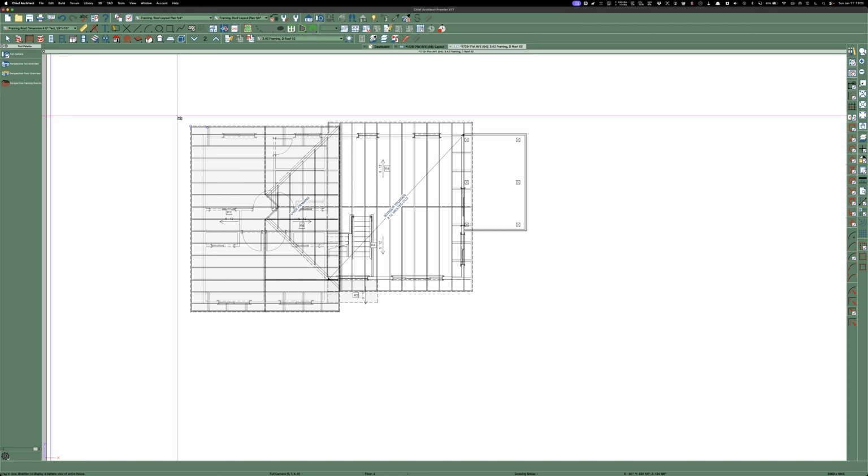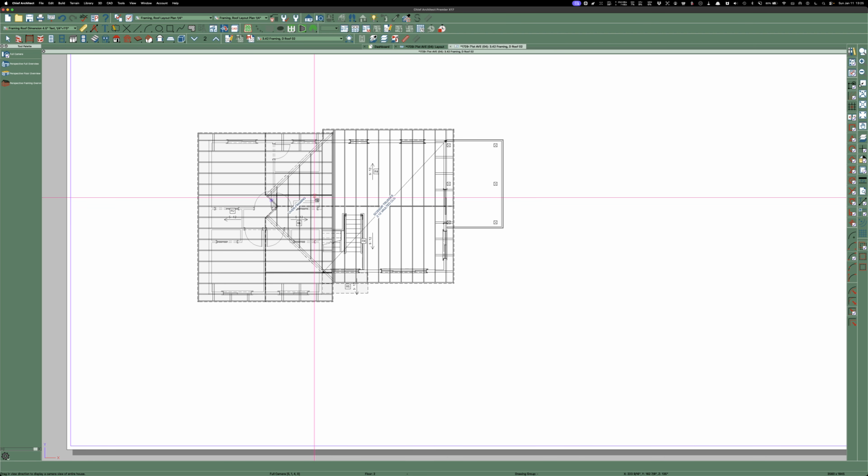Truss guys might be able to do them, but man, there's going to be no repetition. Every single truss is going to be custom, and that gets expensive. And think about it, these are 2x4s mostly. If your house caught on fire, you better get out quick, because once that 2x4 catches fire, it burns through fast. And I don't like 2 feet on center anyways.